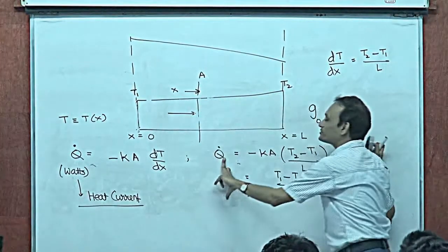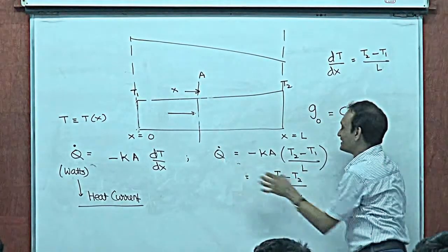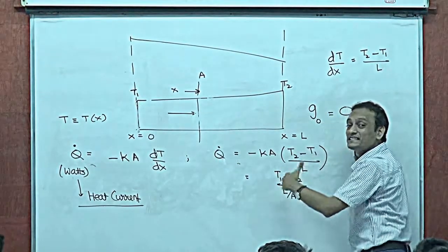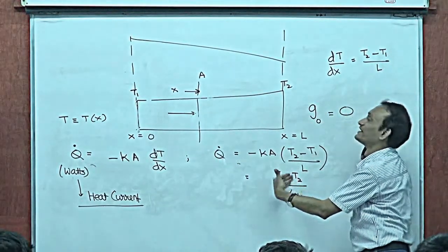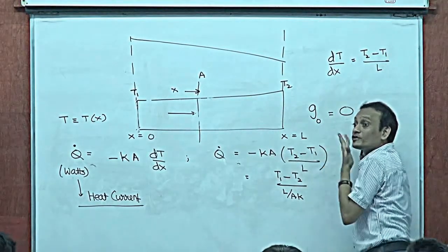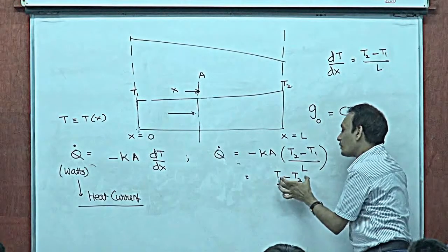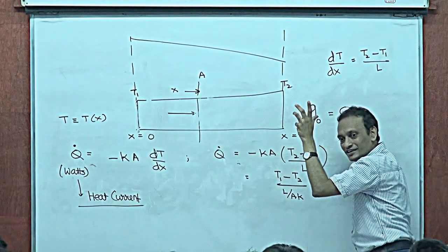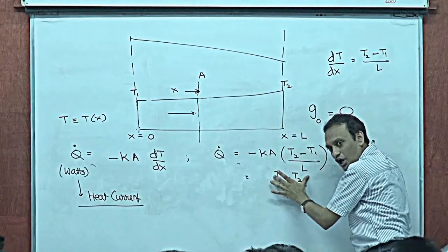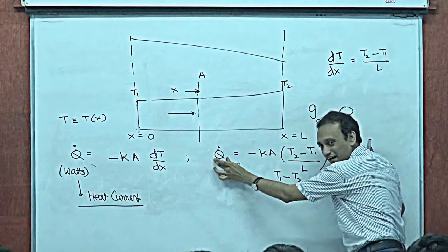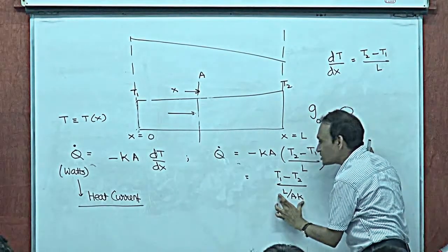Now, the reason we would call it the heat current is that heat has flowed because T1 is greater than T2. That promotes flow of heat from left to right, right? So this is synonymous with potential difference. If this is synonymous with potential difference, we can call it the heat current. Then we could call this the thermal resistance.